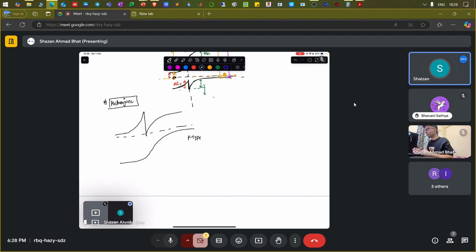This is some heterojunction, let's say this is ND1, and this is the conduction band offset delta EC. This bending is QV2, which is the built-in potential, and let's call this bending QV1. And this particular thing is EC minus EF.